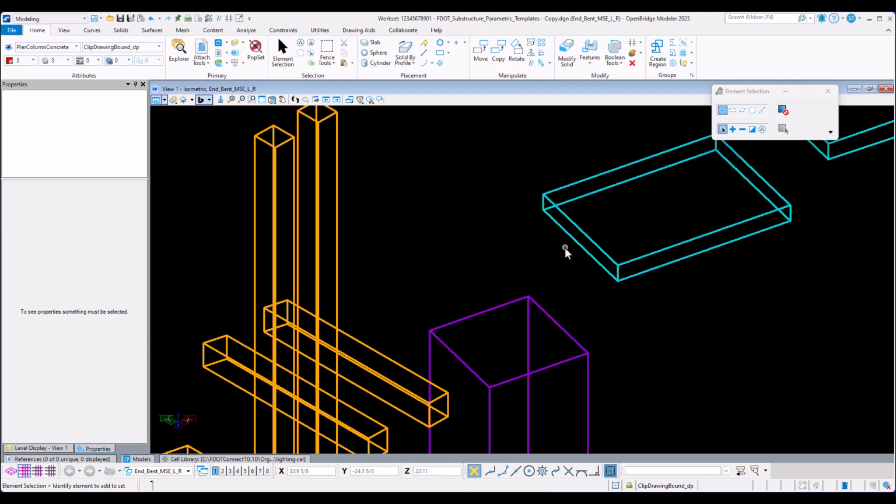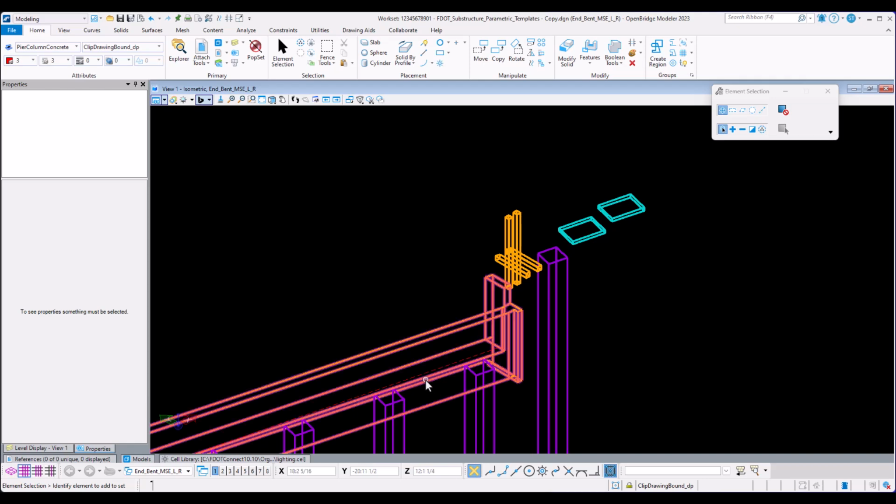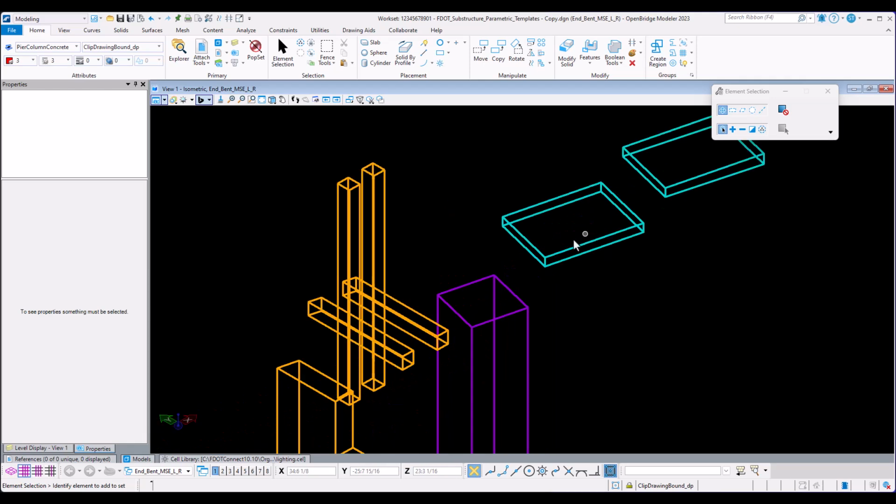The reason we're doing that is because that taper was initially set relative to the orientation of the pedestal, which is not the way that it's relative now to the cap, right? Because we rotated these pedestals after the fact, and that taper was applied before the rotation, so that taper direction was not in the correct direction, and that's why we had to do that.